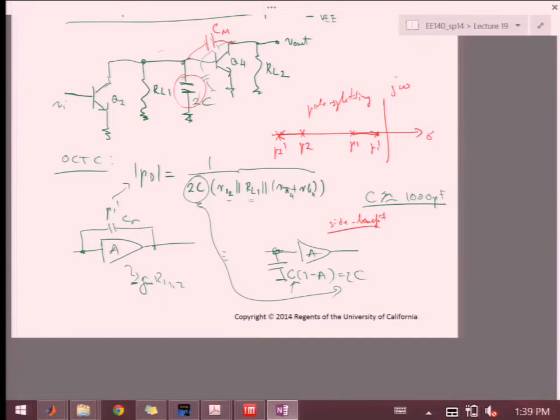And you've also gotten a lot less capacitance to add to the circuit, so now you can think about something that's an integrated circuit. You're talking about C Millers of approximately, let's say, 30 to 50 picofarads. In fact, the early op-amps that were integrated, the first ones, from Analog Devices, had roughly about 30 picofarad capacitances and used exactly this type of effect.